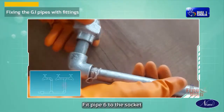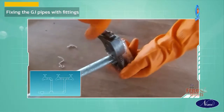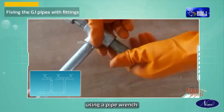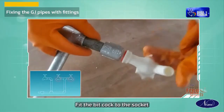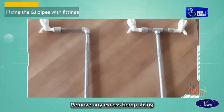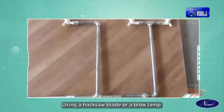Fit pipe 6 to the socket using a pipe wrench. Fit T3 to pipe 6 using a pipe wrench. Fit pipe 7 and 8 to the T using a pipe wrench. Fit the socket to pipe 7 and 8 using a pipe wrench. Fit the bibcock to the sockets using a pipe wrench. Remove any excess hemp, string or sealing tape after completing the joints using a hacksaw blade or a blow lamp.